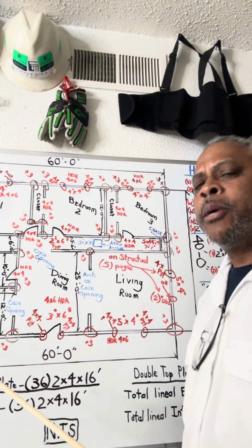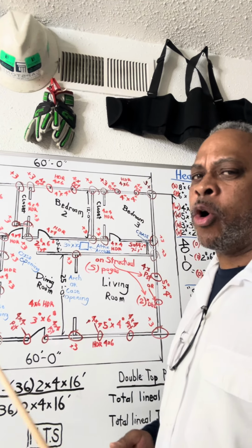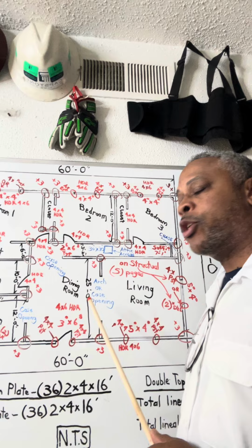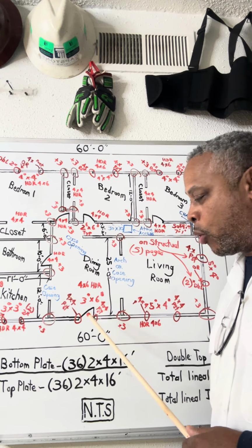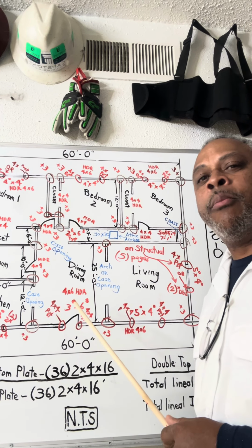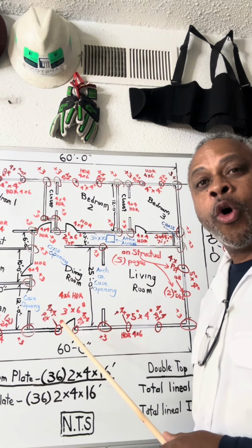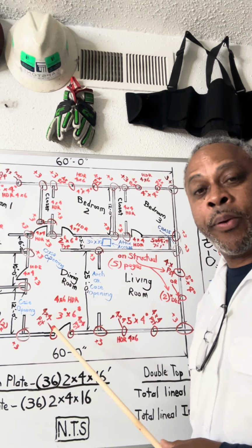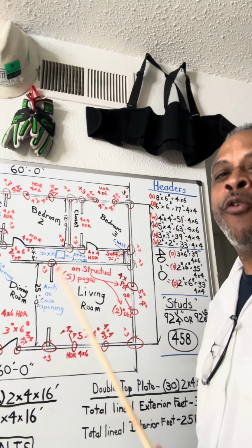Yeah, it is. But you can also have side light panels on each side that can extend that to be over 6 feet. But as a regular standard 3-foot door, or we call 3068 door for the front, sometimes engineers want a bigger header because you can't go with a 4x4 over a 3-foot opening. From anywhere from 1 to 4 feet, 4x4.